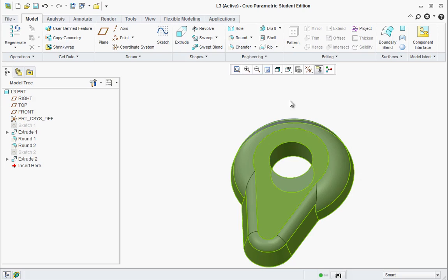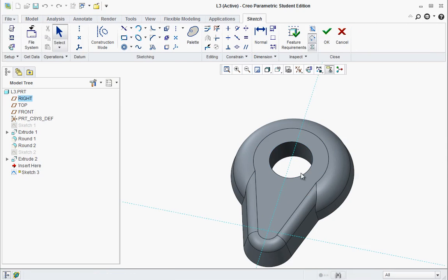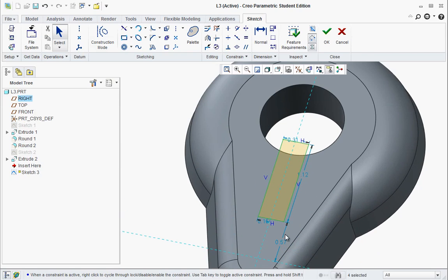Now the next thing after that is go to Sketch, select this face, Sketch, and we're going to go ahead and draw a rectangle in here. Just like that, kind of centered. Eyeballing it right now, but once we get the parameters in, it's going to be 0.25 across, and so it's 0.125 for a halfway marker, and this is going to be 0.2 to the base. And then this length, you could probably make this 2.5. Oh, actually, 1.5. There we go.